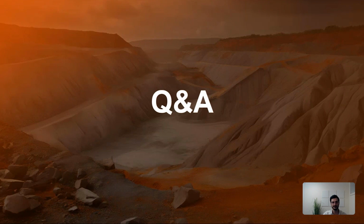And the last question we have here is, which solver is better, iterative or direct solver? So maybe I'm going to pass it to you because we talked about the solvers. It depends, first of all, on the hardware you have on your computer and also the size of the model, in general the number of elements.